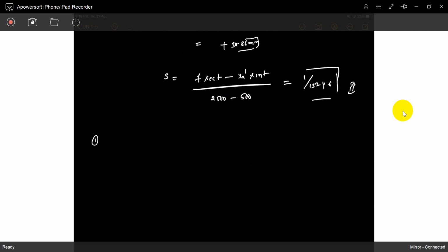So now we can see, determine the length of AB on the ground. We already solved one problem in a vertical photograph, where we calculated the length of AB. If you find the 2 points, we have to find the coordinates on the ground. Later we will use the direct formula, root of (xa minus xb) whole square plus (ya minus yb) whole square. That's it.